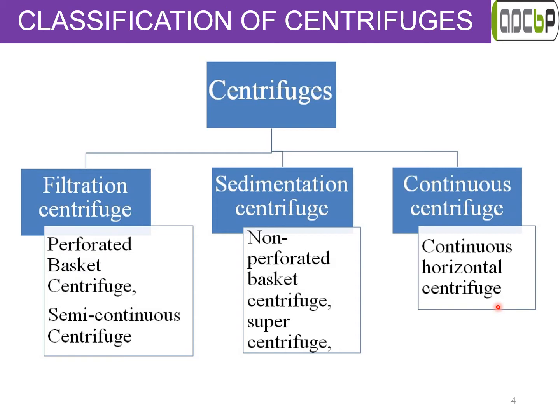These are very rapidly acting centrifuges. They require high maintenance due to wear and tear of the perforated baskets, and the removal of residue or solid after separation is somewhat difficult as it is stuck or entangled in the perforations.